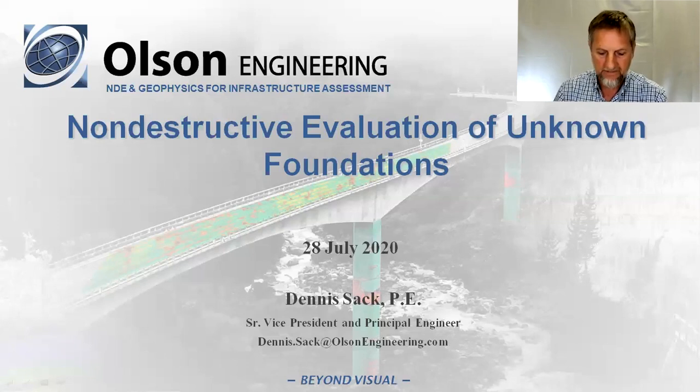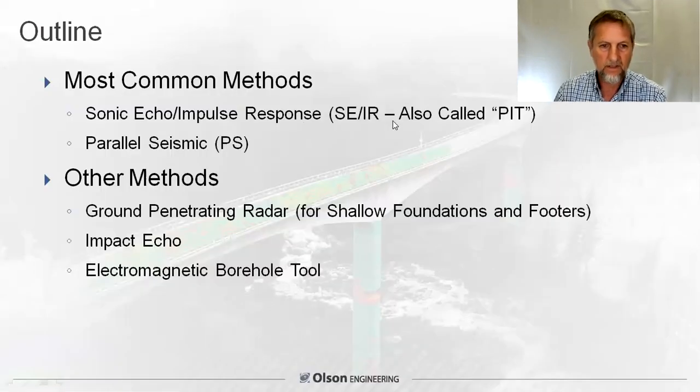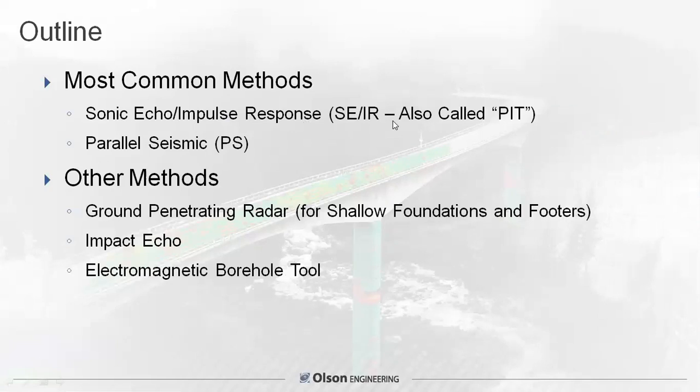Again, we're going to be discussing the evaluation of unknown foundations. There are 5 methods we're going to be discussing today. The most common methods are sonic echo, impulse response. This is also the method called the pile integrity test method, PIT. And the other common method is the parallel seismic method, or the PS method.